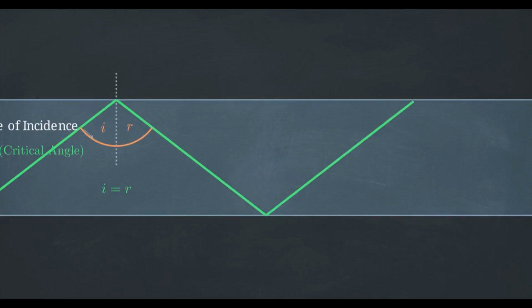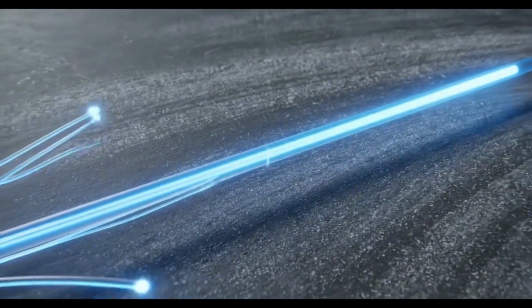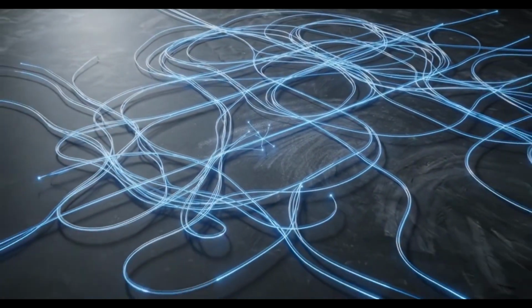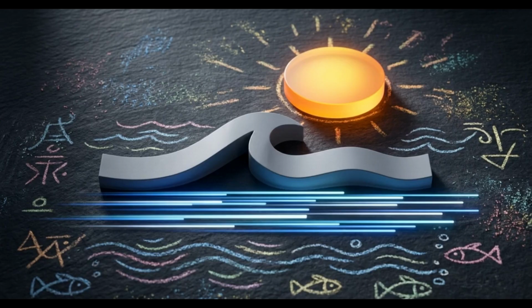The light perfectly reflects, causing a continuous ricochet down the fiber. Because of total internal reflection, no light refracts into the cladding. 100% of the signal is retained as it travels over vast distances. Mastering the geometry of a single bouncing light ray is the foundational physics that allows the internet to travel across oceans at the speed of light.